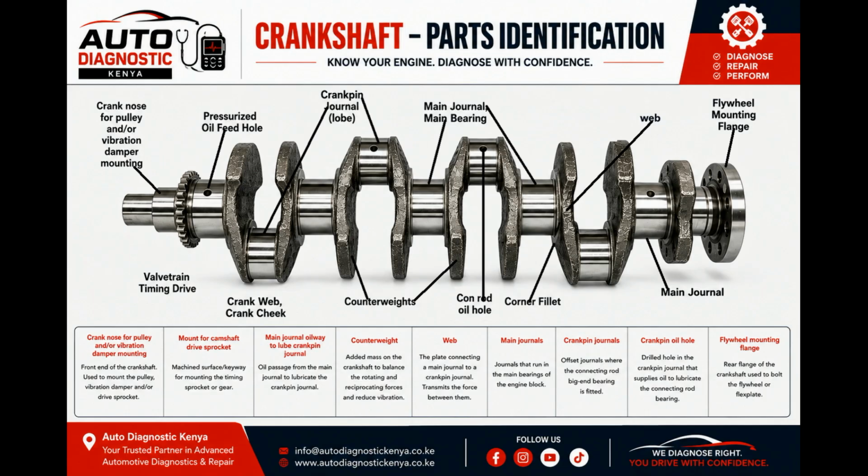Next, we have the flinger ring and scroll seal. These are other methods too. One is a flinger ring. It's basically a thin ring or fin found around the crankshaft. As the crankshaft rotates, centrifugal force throws oil away from the shaft. The oil is collected in a cavity, and a drain hole allows it to return to the crankcase. Another method is the scroll.